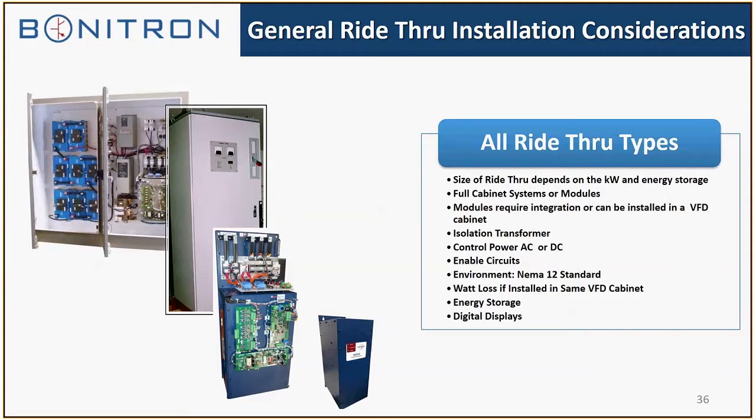If you're going to install the ride-through in a cabinet with the drive, the watt losses aren't that great, but you should consider it if the drive cabinet's already pretty tight. The drive's going to have some heat, so the ride-through will add to it about the same amount as the drive. So it's just a consideration. And then energy storage and the type of displays. That's pretty much the general things for any of the ride-through solutions, and we can take most of that information and hammer it into a solution for an end user.